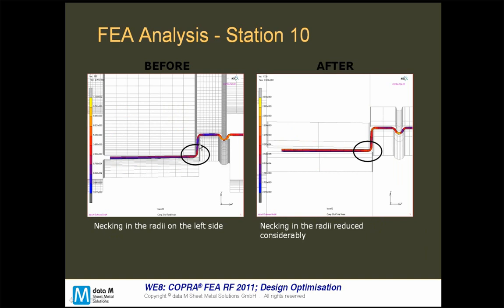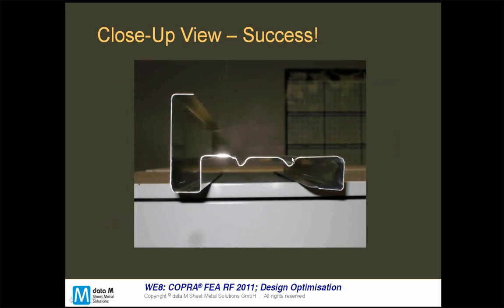the material thinning we get at the bends. Before changing this material flow, the bend steps were not constant like 5 degree or 15 degree steps, but really letting Copra create the bend steps. The issues were much lower, and at the end it made the profile stability much better after the cut-off also, and the end flare issues were minimized.